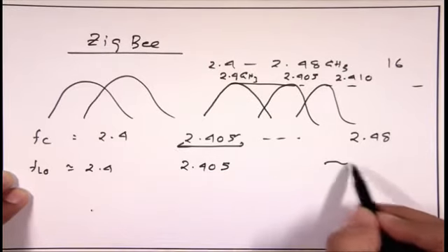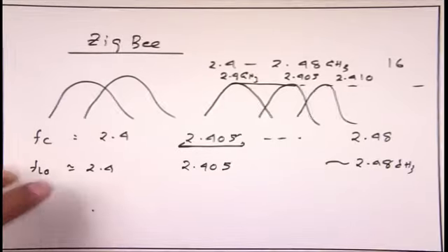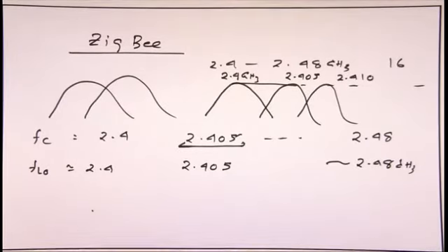So you have to give a local oscillator frequency of 2.48 gigahertz, yes or no? So you need to generate the local oscillator frequency with the same 5 megahertz spacing, 2.4 to 2.48 gigahertz. Who will do that? I told you to design a VCO. That VCO can develop this 2.4 with a tuning range of this fine tuning and so on. But that frequency should be stable.